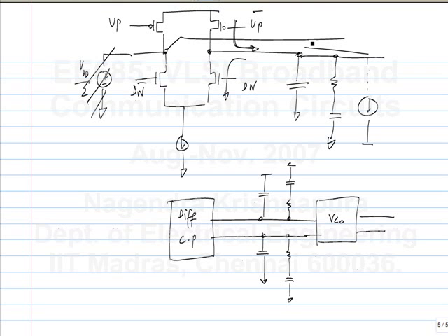Yeah, so this is a 3-state phase detector. We saw that it will tend to go to one state when edges of A are more frequent than edges of B. Now if you have clock and data, the number of edges in the clock is definitely much more than the number of edges in data. So it will always go to one side. So this will not work for random data. How would you make it work for random data?